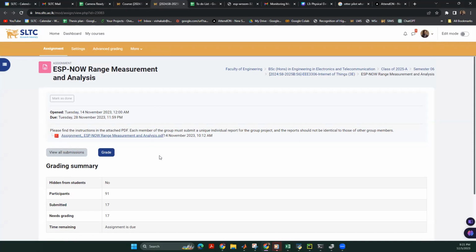It is essential for us to understand up to how long, or what coverage, we can do the communication using the ESP-NOW protocol. So this assignment is on that. I'm asking you to create an ESP-NOW protocol based test, and understand the maximum distance up to which this ESP can communicate.